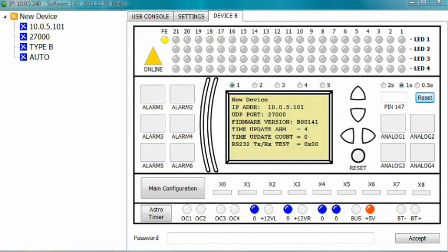For example, you can set up the alarm zone in such a way that you can only arm the alarm in the common corridor once all the other alarm zones are armed. This would also automatically disarm the corridor alarm once an alarm in one of the rooms is disarmed.